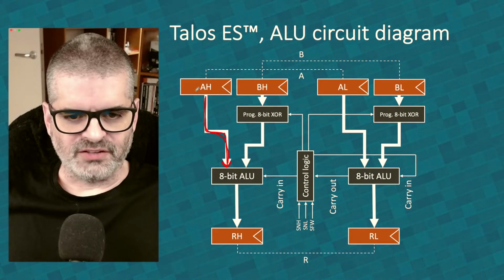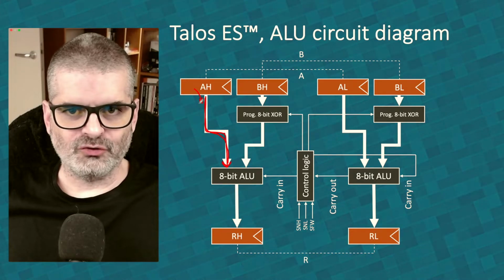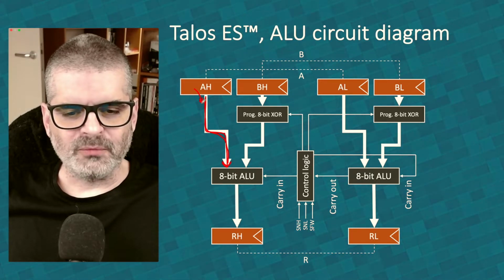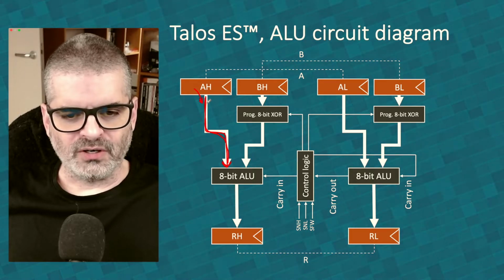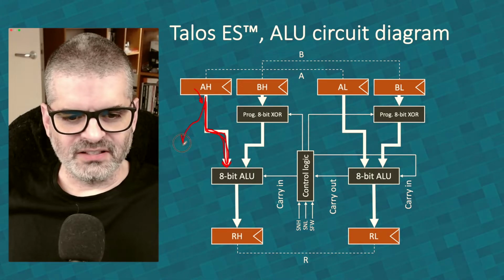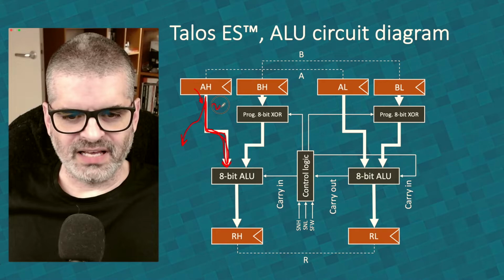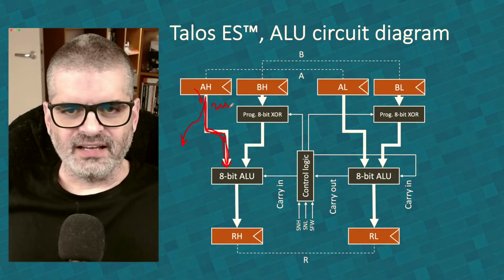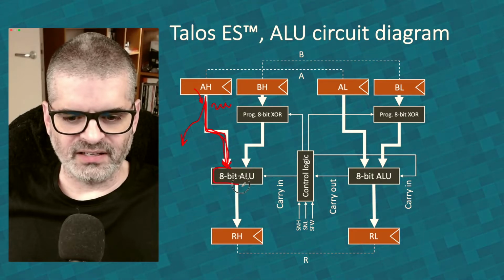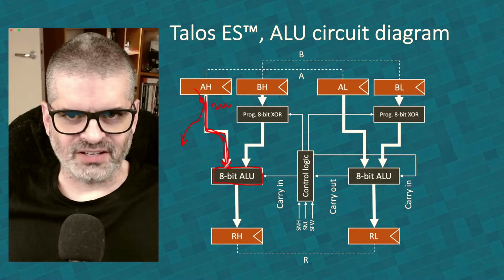So the chip that's driving the line doesn't have to source a lot of current and can maintain the voltage level pretty stable. But when you are driving a logic load and LEDs, then the current draw is much higher and the voltage level will fluctuate. And if it fluctuates, you can't guarantee what the next chip in line is seeing and how it will interpret the levels, as low or as high.